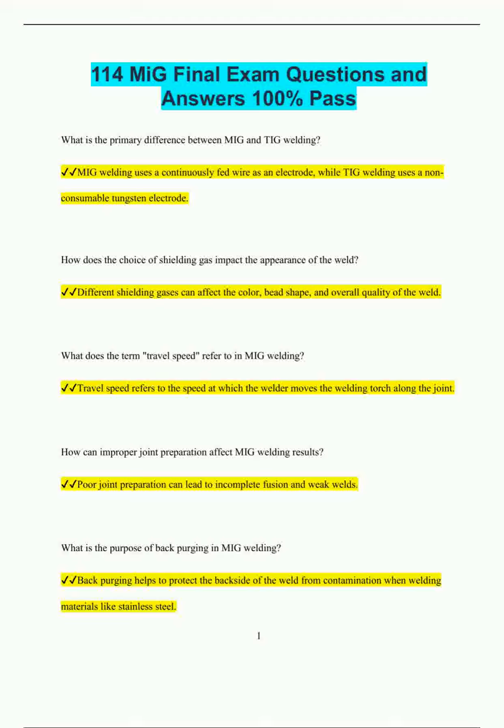What is the purpose of back purging in MIG welding? Back purging helps to protect the backside of the weld from contamination when welding materials like stainless steel.